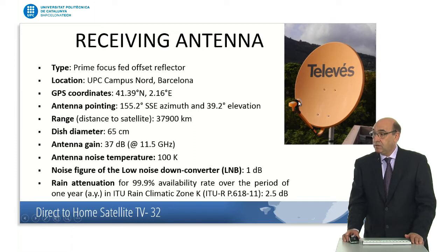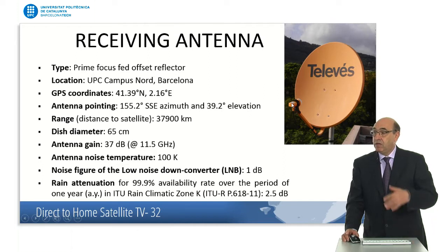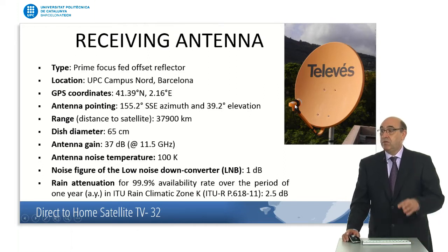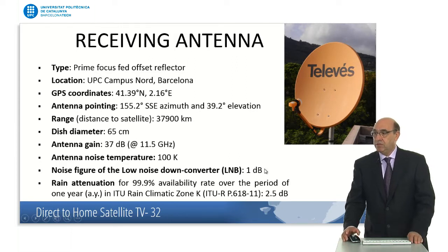And here they are going to perform frequency shifting and bring the received frequency from the satellite to the first intermediate frequency. Now, in this process, there's a lot of gain here, but there's also some added noise. I'm taking a noise figure of 1 dB, although the nominal value you may see in those receivers could be 0.3, 0.4 dB, but let's take just 1 dB to make things simpler in the calculation.